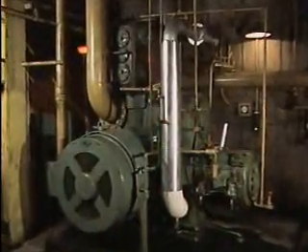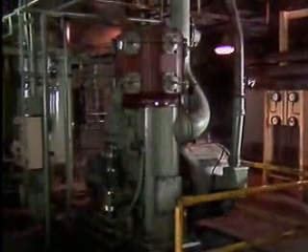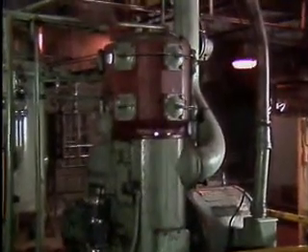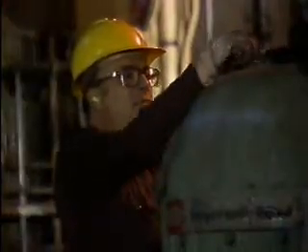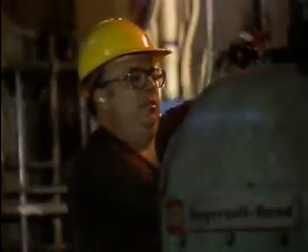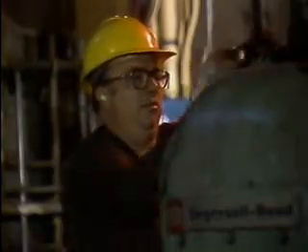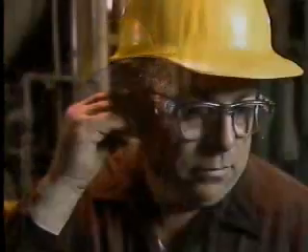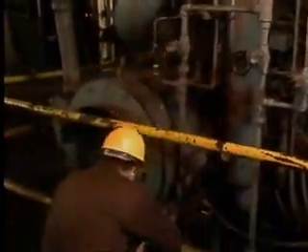Compressors can also be hazardous because heat is generated when gas is compressed. The outside surfaces of a compressor can get very hot, so be careful not to come in contact with the hot surfaces. To lessen the risk of getting burned, it's a good idea to wear long-sleeve shirts made of cotton or other natural fibers. The sleeves should be rolled down and cuffs buttoned whenever you're working around operating compressors. Compressors are also extremely noisy. Personnel who do not wear appropriate hearing protection may risk a permanent hearing loss.